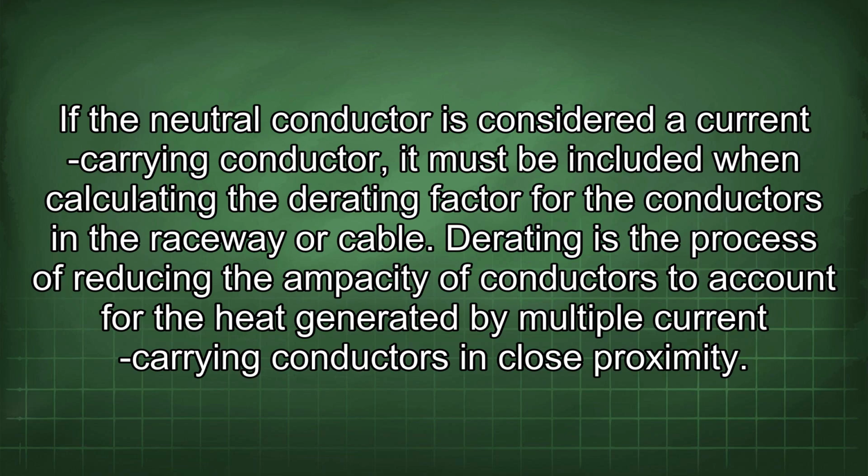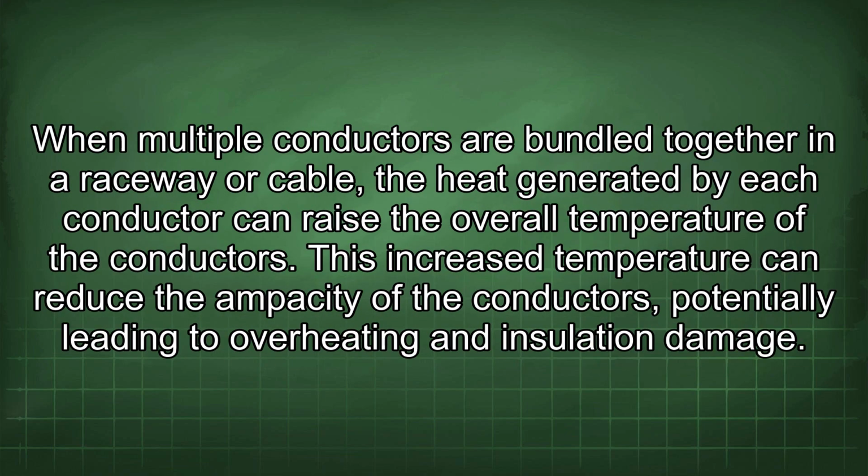Derating is the process of reducing the ampacity of conductors to account for the heat generated by multiple current-carrying conductors in close proximity. When multiple conductors are bundled together in a raceway or cable, the heat generated by each conductor can raise the overall temperature of the conductors. This increased temperature can reduce the ampacity of the conductors, potentially leading to overheating and insulation damage.